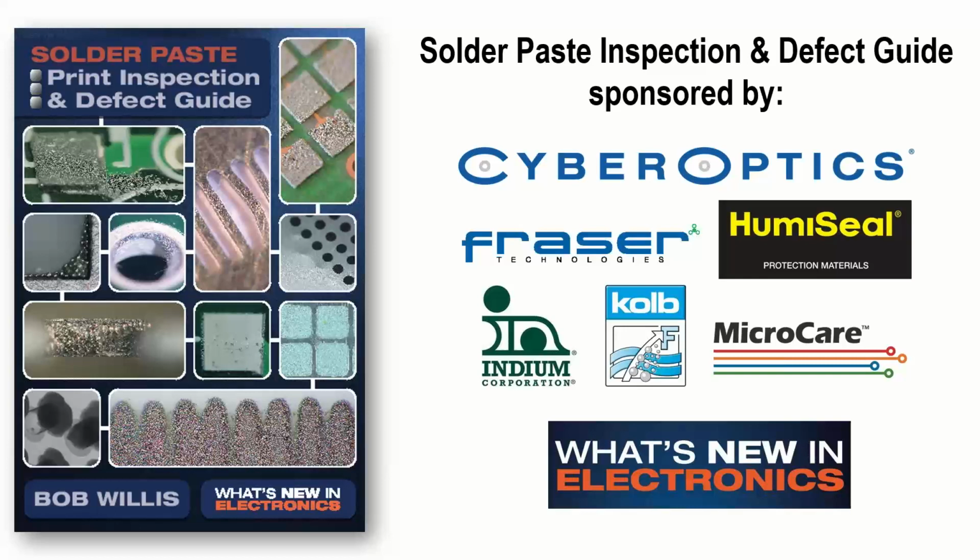What is the effect of using incorrect squeegee size versus PCB panel size? Well, really, the squeegee, you should be printing where you're printing the apertures on the board. So let's say you've got a 10-inch board and the print area is 8 inches, then the squeegee blade may be just slightly larger than the 8 inches. You're not going to have to necessarily print across a 10-inch surface.